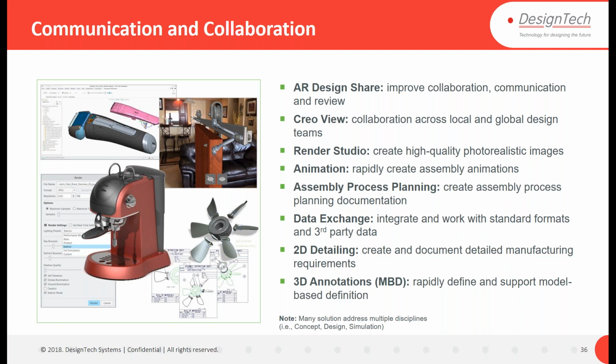You can also create 3D annotations, which is very important when you are going for model based definitions. It is important that you create all the annotations right on the model, and that model will become a single source of truth. That model can be used for creating a drawing, for doing tolerance stack up, for CMM inspections, and for CMM programming.